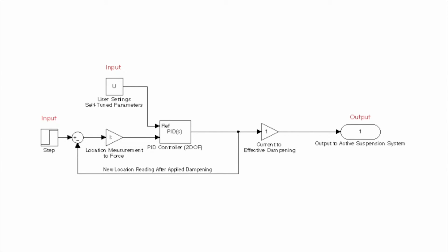This is the simulated block diagram of the system, which is controlled by a specialized PID controller. The PID does not have a single setting but multiple inputs to determine the values of its P, I, and D coefficients. These inputs include user settings, steering wheel inputs, and other vehicle stability control parameters. For steady forces imparted on the system, in maneuvers such as turning, the proportional term is increased to decrease the current state of error until the deflection returns to zero.